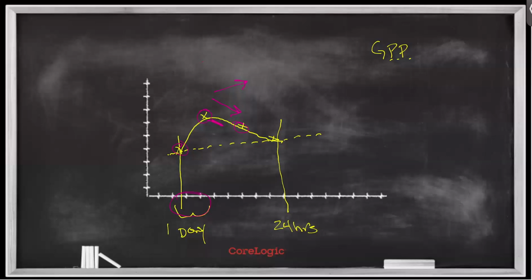And that's kind of a catch-22 because if I don't have good humidity control for the first 24 hours of a drying project, not only do you run the risk of damages beginning to occur, but secondarily, you run into an even more significant problem, quite frankly, and that is that if it's really humid in that environment, your evaporation rates aren't maximized because the humidity is too high, and water is not just leaving the materials at that point; it's also absorbing deeper into those assemblies.